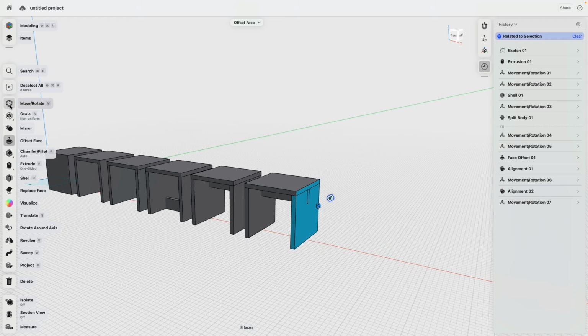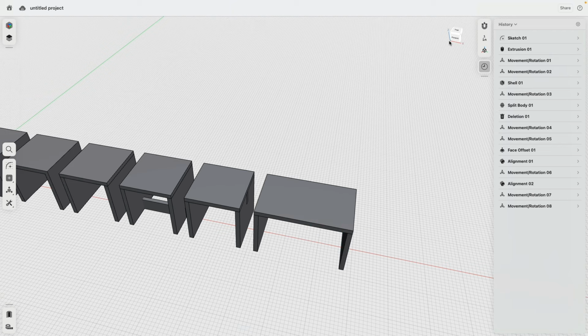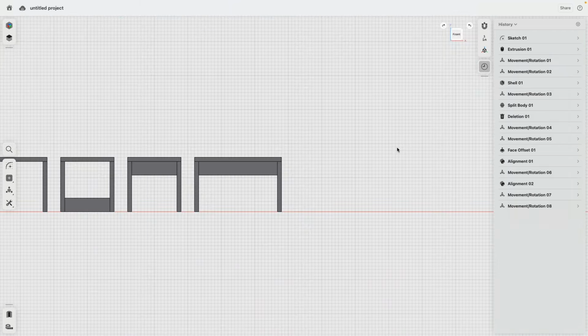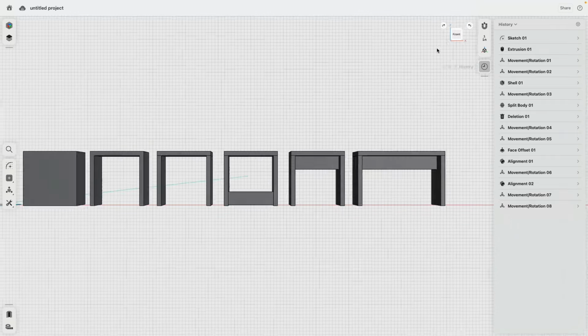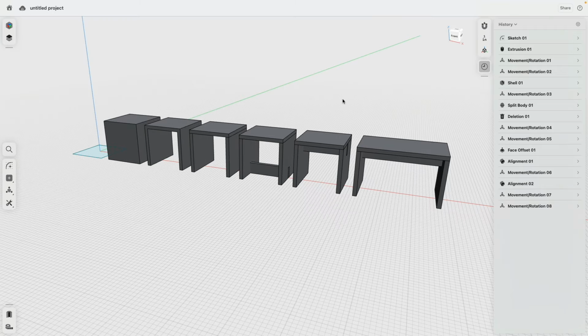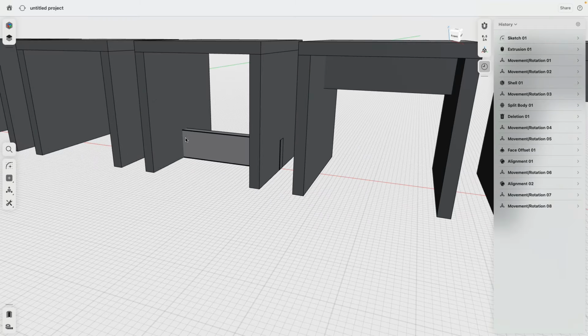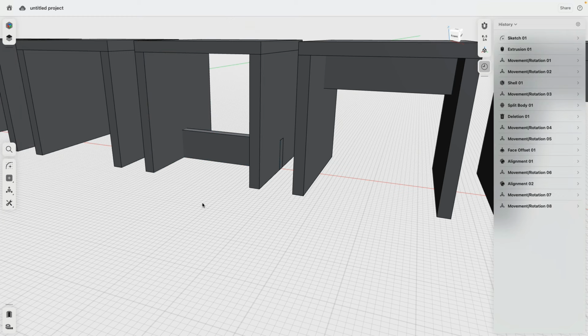Then go to move command. See, 2 cubes to the grid. Block, block, block, block. There, 10 inches. Now we actually made this whole bench 10 inches wider. It looks actually pretty cool. Yeah. At this point, we can see that this piece intersects with that, but there's no hole really cut out.